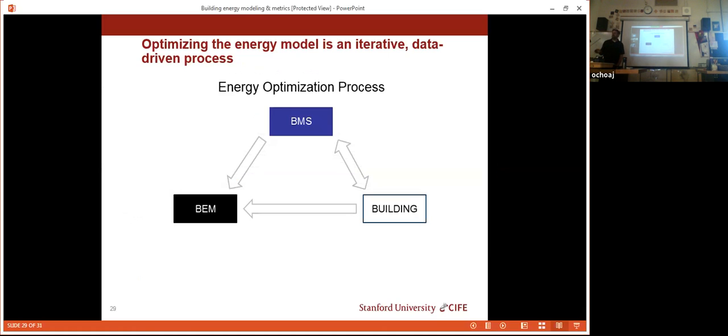So you remember Filippo, when Filippo talked, he came in and he talked about optimization. And so when you talk about optimization, what you're talking about is using different types of algorithms to take that building, that energy model, and looking for the best solution. So you take a building, I think that's building energy model, building BMS. Building management systems. Okay. So I think this is optimizing the building after it's built. This is the calibration process. So you take the building management system, and based on the building energy management output, you can look at how the building is performing, and there you start changing the set points.